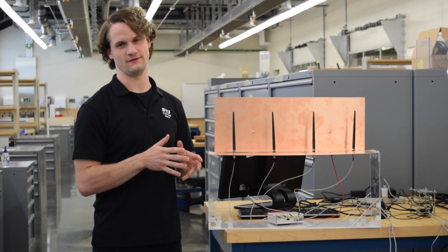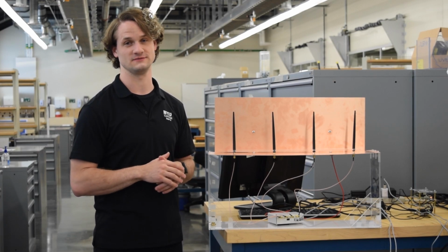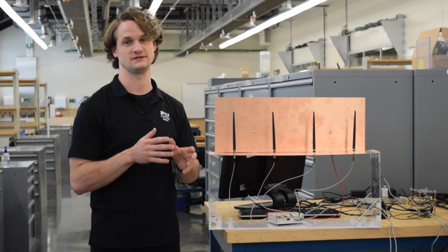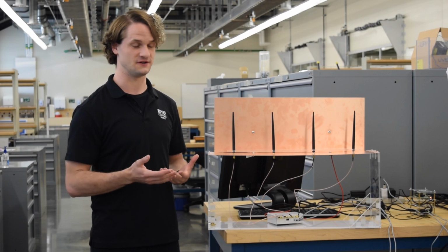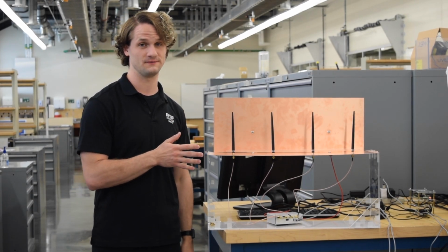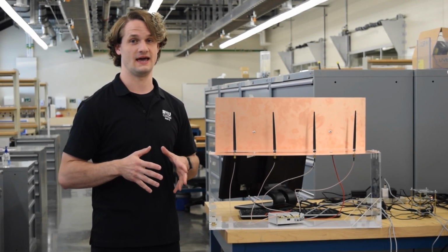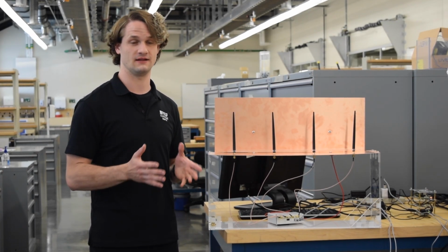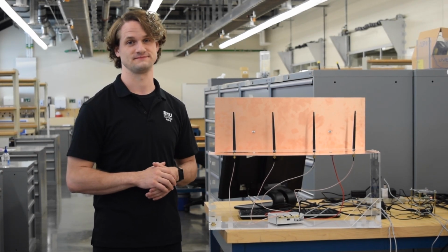With the software-defined radio, there are several different algorithms that we can use to calculate the direction of arrival. After doing some research, we decided on the MUSIC algorithm, as it's the most popular and it cuts down on noise and allows for clean angle estimation.